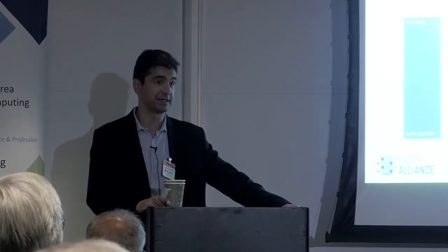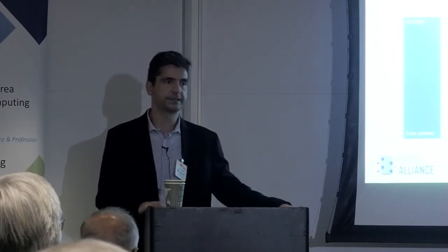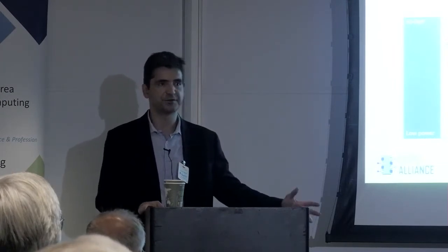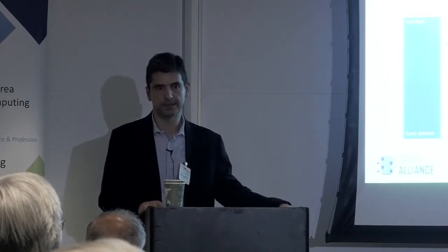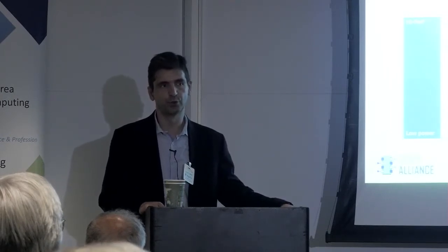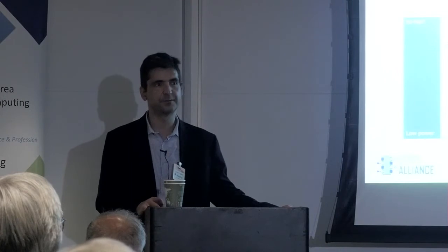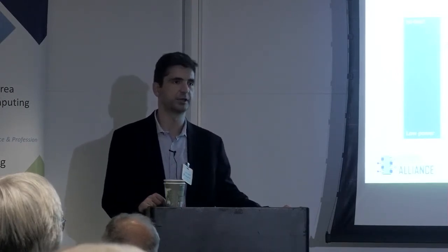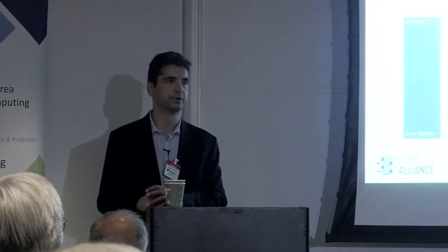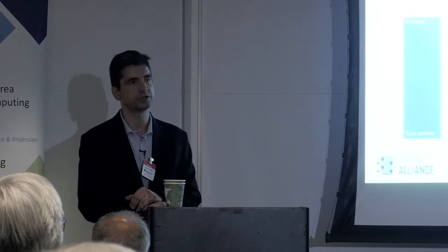The CHIPS Alliance is actually looking into this specific problem. With the help of Google, I don't have a chart on this, but there's a cool tool called STIG that's available through the cloud that uses the Verilator RTL simulator and Imperas's golden model instruction set simulator to run a similarly stressful test, trying to go randomly through all the instructions.